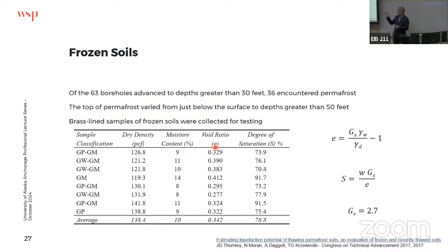And then like say the 64 earthquake, we had this clay layer that had what we call cyclic softening, right? And so when you start talking about cyclic softening versus liquefaction, now you're kind of splitting hairs. And some of us get up in the morning because we like to split those hairs. But you have this kind of liquefaction spectrum, right? Where if I asked you, do gravels liquefy? What would you say? Yes, no?